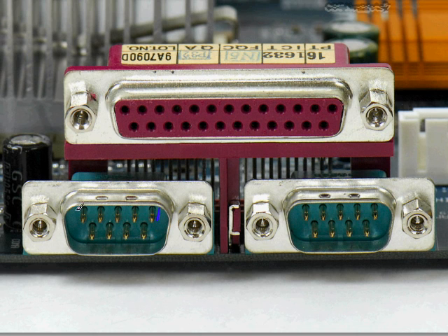Notice the D shell shape, remember it's a DB9, the D being a D shell. It's a little wider up at the top, and if you turn your head to the side and use your imagination, it looks a little bit like a D. That's pin 1. That's pin 2 right there. That's pin 3 right there. Pin 2 is normally used to receive data. Pin 3 is normally used to transmit data.